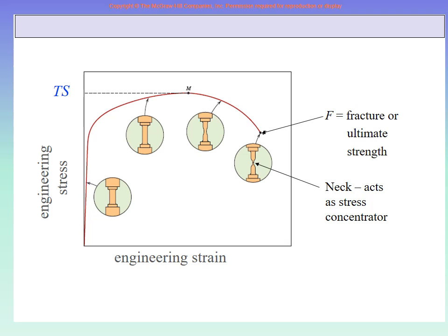You see, the head and face is a bigger size, the shoulder is a bigger size, the neck in between is a smaller size. So this is the neck area, and forming of this neck is called necking, right? So once the ultimate stress point is reached and you further load it, then necking starts to happen because the material has become very weak.